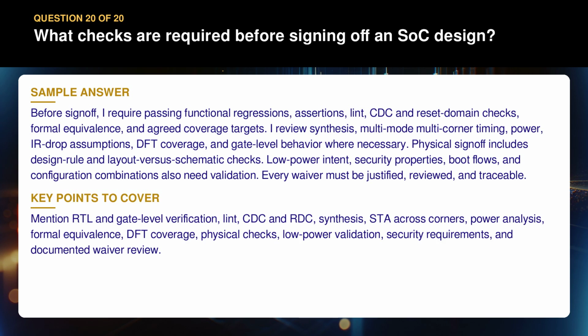Mention RTL and gate level verification, lint, CDC and RDC, synthesis, STA across corners, power analysis, formal equivalence, DFT coverage, physical checks, low power validation, security requirements, and documented waiver review.